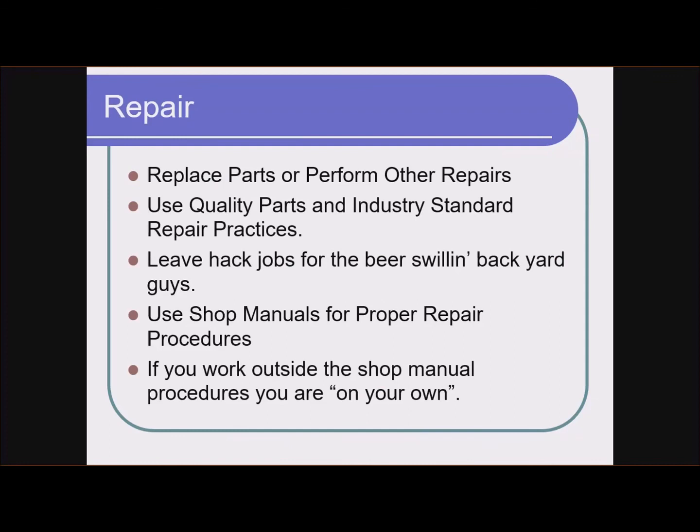And then the other part, industry standard repair practices. A heater core, as an example, can be extremely difficult to replace. It means removing the entire instrument panel, the entire dashboard from the car, removing the heater box, getting it out on the bench, separating it, replacing the heater core, putting it all back together.